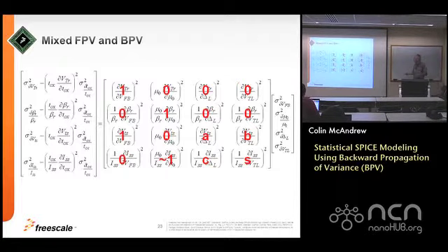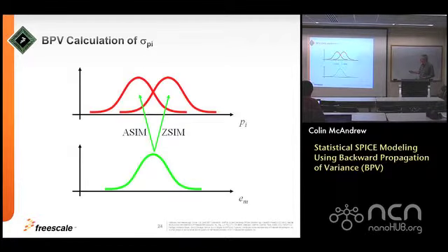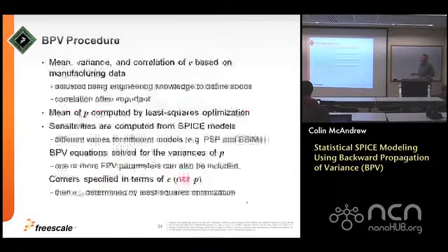So you can actually look at this set of matrix equations and you can work out up front what it should be. But that's sort of it in a nutshell. That's how the procedure works. And then we generate these things based on engineering understanding and manufacturing data, and then we calculate what those sigmas are, and that gives us the sigma values. So basically what we're doing is we're taking the results that we want and we're force-fitting the variations in the parameters to give us those results.